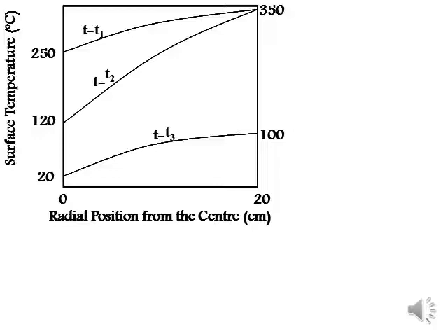Even in the latter moment at t equal t2, you will find that the point in immediate contact, the point of impingement, comes down further to 120, a stronger replacement and stronger cooling by a new mass of water, while the farthest point is still at 350.